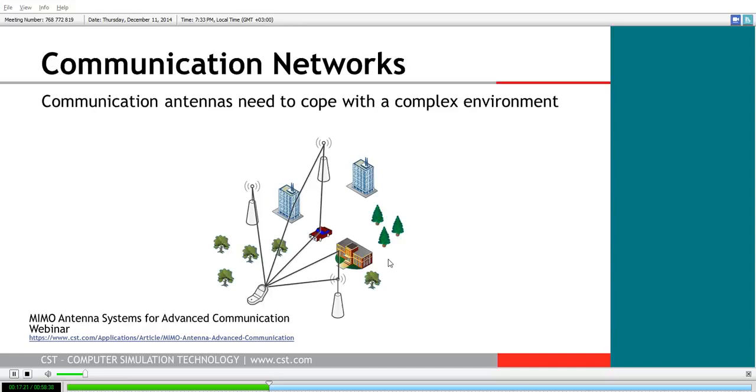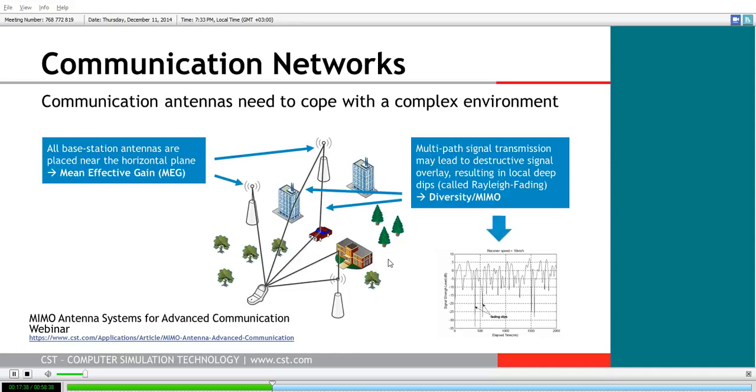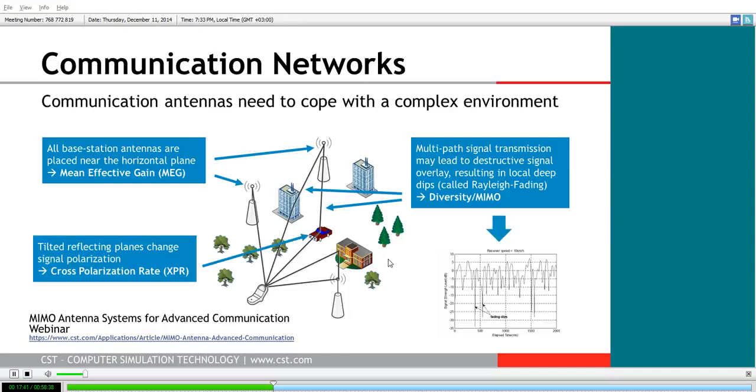And the slight delay in transit times that these different paths have, because they have different path lengths, this can mean that the received signals have the potential to interfere destructively with one another and cause a dip in the received signal and potentially a dropped call or a loss of data signal. Of course, that's just a path consideration, but there's also polarization decay rates as well that can individually be accounted for in models as well.